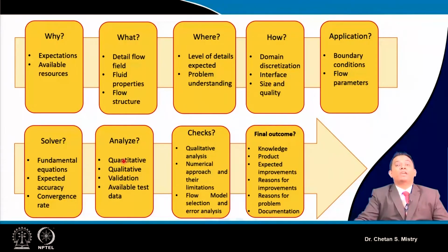Based on that, you make your blade geometry. After making that blade geometry, you analyze your blades, and that gives what we are looking for in terms of performance of those blades, or the rotor and stator combination, or that stage or multi-stage configuration. So do not be under the misconception that CFD is a design tool. Rather we can say CFD is a design improvement tool.